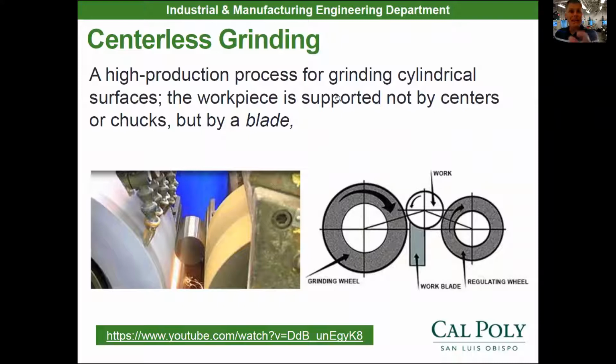So if we had to make like a dowel pin, like we're pressing into our Geneva fixture, you're going to see we have this Geneva-based fixture here that you use to inspect your Geneva base, or you will when you get to that lab. And we have hardened steel dowel pins in here that, well, you really can't see it, but the hardened steel dowel pins were ground down to a 0.145 diameter. We went from 3/16, 0.1875, down to 0.145.